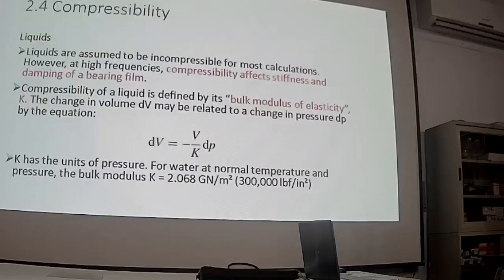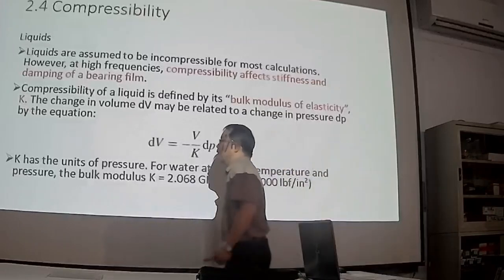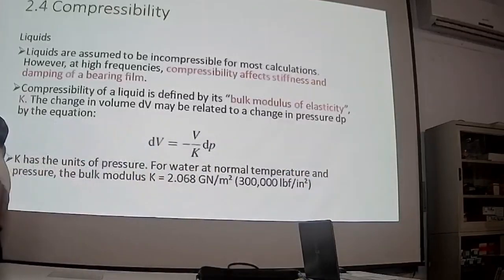So here is the measurement for the compressibility. Liquid is assumed to be incompressible in most configurations. In our case, for the hydrostatic bearing, this holds if the supply pressure is lower than 80 bar. This is a rule of thumb.